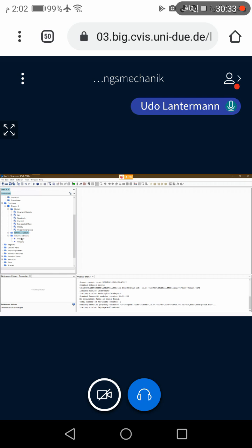And for initial conditions, we need an initial condition for pressure and velocity. So for initialization, we start with pressure 0 Pascal, and also velocity of 0 meter per second. Okay, it's only for initialization. We start with the whole field equal to 0 for the pressure and also for the velocity. Then we have created our physical models. We've chosen our physical models.